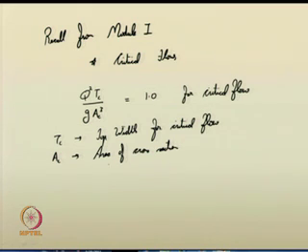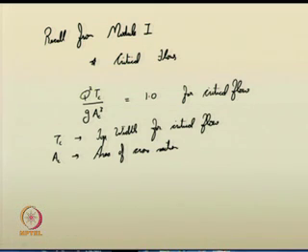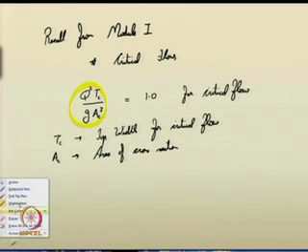This entire quantity was almost related with the Froude number also, and for critical flow this quantity is equal to 1. So, if you recall this, it is now quite easy to incorporate similar principles in the dynamic equation for gradually varied flow.